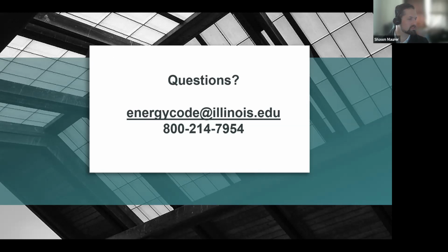We did have a question come in about the length of time it takes to do the test. For residential homes, I used to do that testing, and it would take about 30 to 45 minutes to set up the test, walking through the house, making sure things are properly sealed, windows are locked, that kind of thing. Depends on the size of the house too. A larger home would take a little bit more time. But figure around a 2,000 square foot house takes about 45 minutes to set the test up.